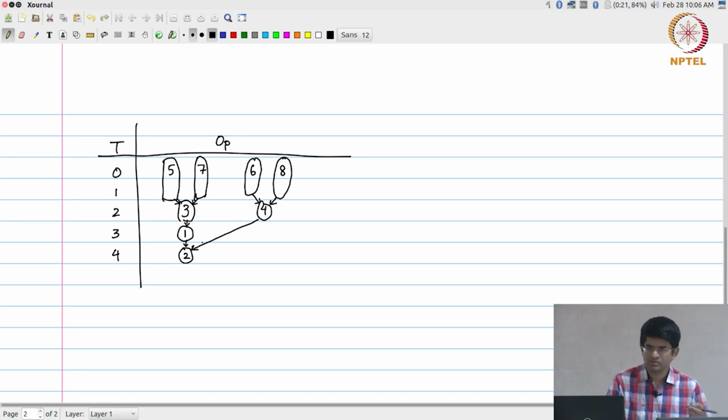Now this is essentially the same kind of analysis that you would do in the case of a combinational circuit, right. I mean, if you had multiple paths through a combinational circuit that are converging at an AND gate, for example, you would take the different paths, and the starting time of the AND gate, so to say, is considered to be the point when all its inputs are ready and stable, and from that point onwards you add the propagation delay of the AND gate and say after that much delay the output of the AND gate can be considered to be actually stable, right.